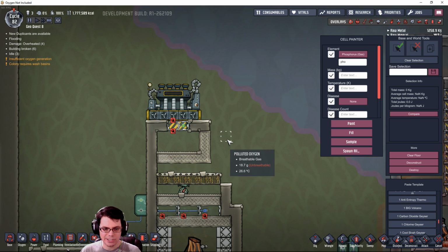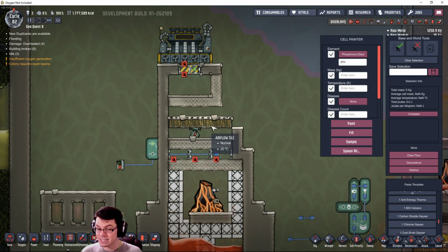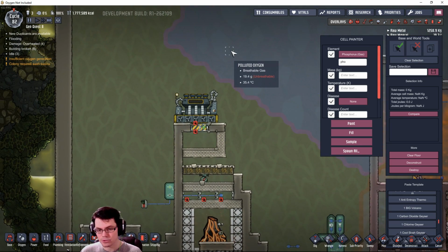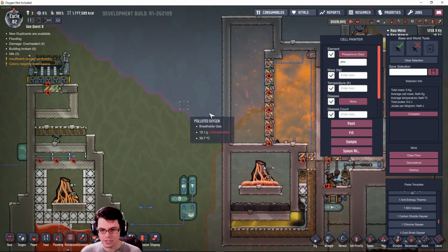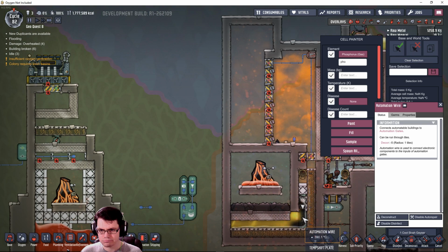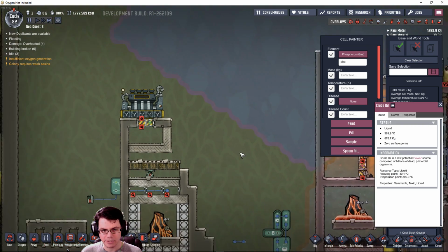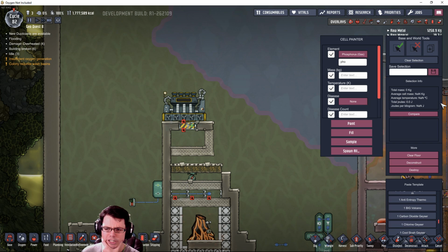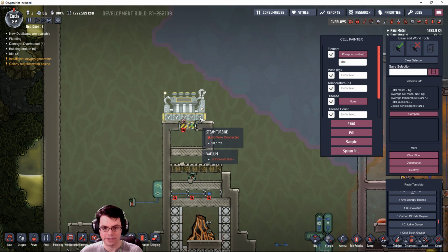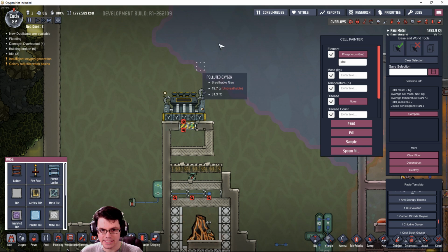So the key here is maybe we can get it down to 250, and then maybe we can get the natural gas, by the time it gets to the top, once we get it through the pre-cooling chambers for the natural crude oil, the crude oil preheaters, hopefully down to around 100 degrees Celsius or lower at the top of the system, so that our pumps and everything are safe. So we will need a condenser up top.